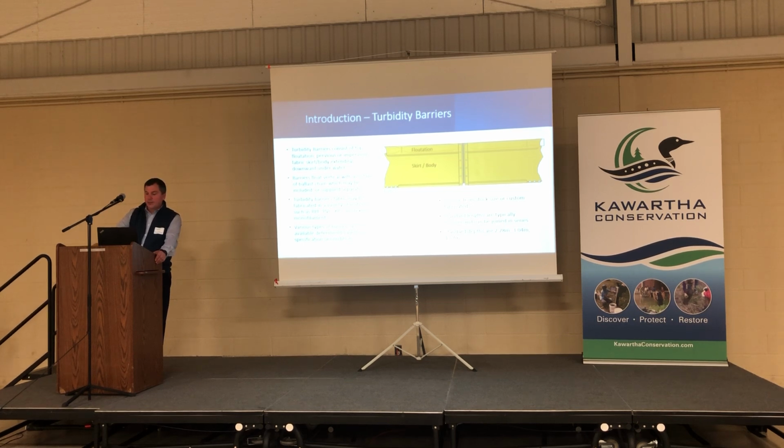There's a variety of different types of materials that the barriers can be manufactured from, and those include products such as RPE, or reinforced polyethylene, PVC, or for longer-term permanent applications, we use a material called XR5, and these are applications that are in service for over 5 years. So the type of material that you're using in your barrier will determine how long this barrier is going to be in service for.